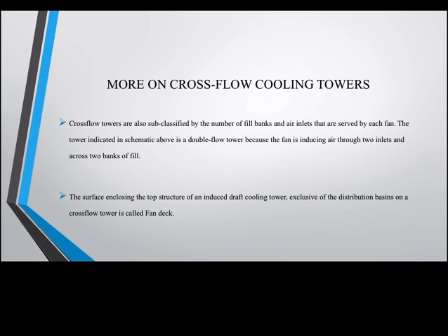More on cross-flow cooling towers. Cross-flow towers are also sub-classified by the number of fill banks and air inlets that are served by each fan. The tower indicated in the schematic above is a double flow tower because the fan is inducing air through two inlets and across two banks of fill.